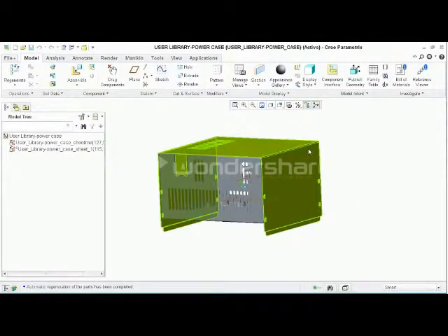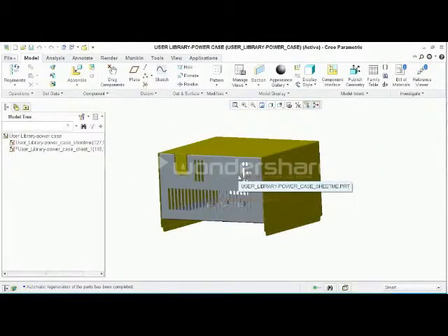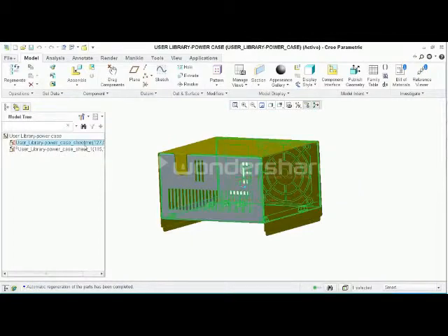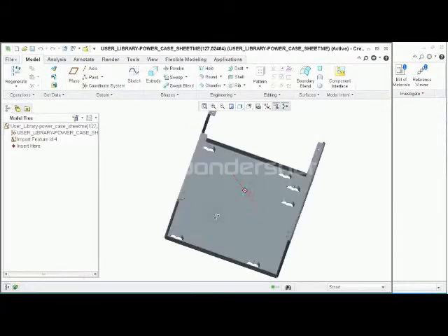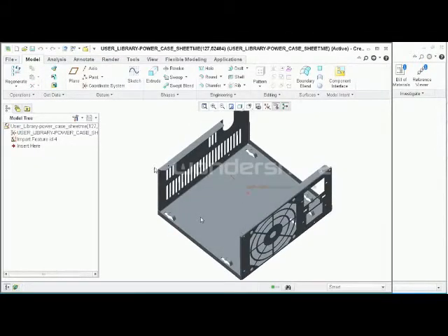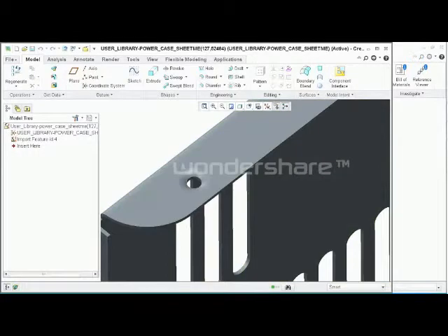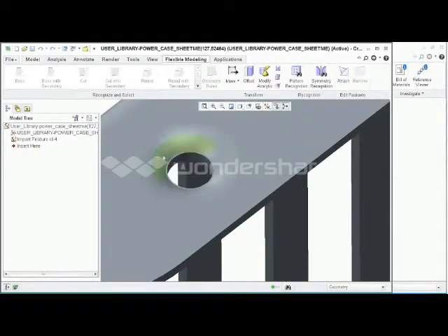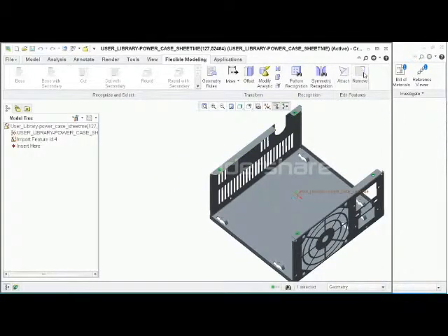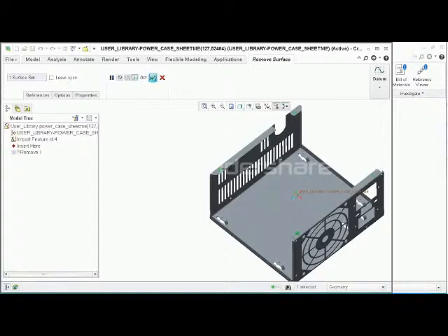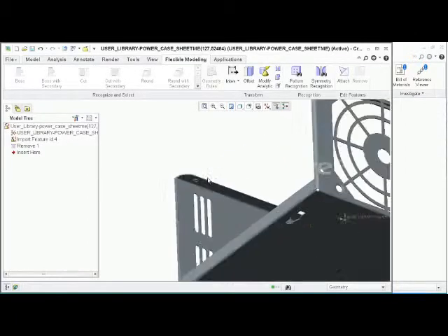Let's bring up that second component, perform an open here, and then perform some very similar operations to make that fit with the other cover. So we're going to go in, again, flexible modeling. I'm going to get rid of these tabs on this as well. Going to do a remove. Now there's actually 4 of them as well, which fits onto the other part. So we're going to remove those. And same thing on the bottom side of this. Geometry rules to grab them all, do a remove.